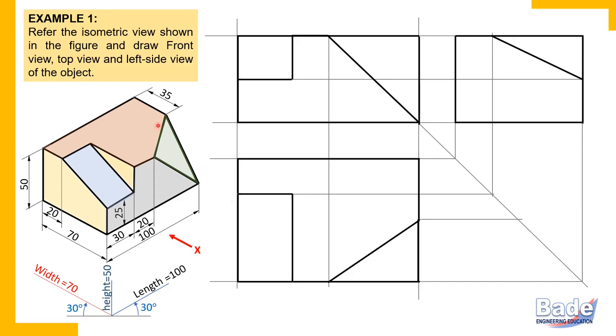Now we got this corner and this corner. These three corners are to be connected. Okay. Now let's focus on this corner. Where is this corner? So first thing is, this corner is at top and on the front. So at top and on the front, whether this corner is at extreme right or extreme left or in between, you need not worry about its position along the length axis, because length does not appear.